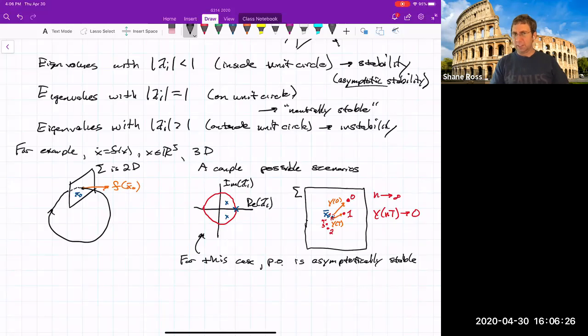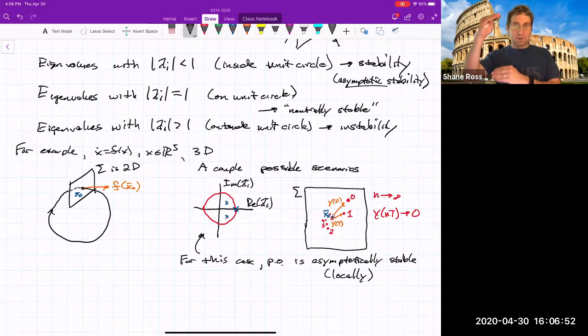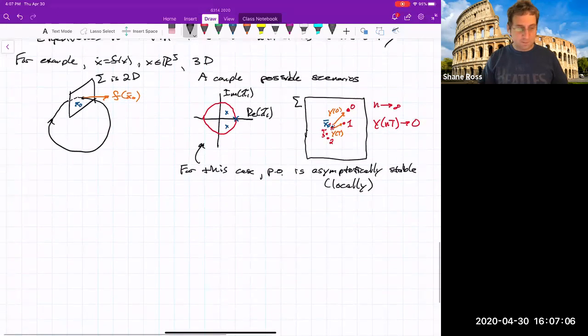That doesn't mean it's globally stable. That's another concept. What we are determining is local stability, meaning locally in phase space. There might be some other periodic orbit that is also asymptotically stable. In fact, those periodic orbits we were looking at as part of the Duffing system, where we had the tilted resonance curve, had 2 asymptotically stable periodic orbits that were separated by an unstable periodic orbit. So those 2 were locally stable, meaning if you started near them, you would get attracted to them. And that's what allowed the hysteresis effect to be seen for those who did that.